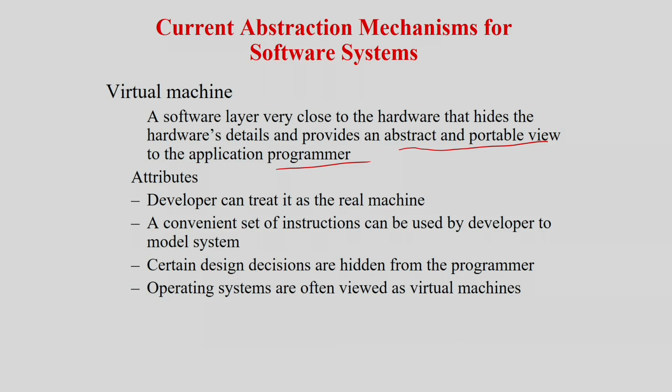So basically all the co-simulation environments work on that. The hardware is written by a hardware person in Verilog, but the co-simulation environment abstracts out the hardware part from the software part. So the software developer will find that the hardware is already there in place, which can execute the software.